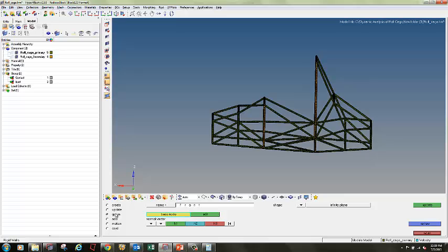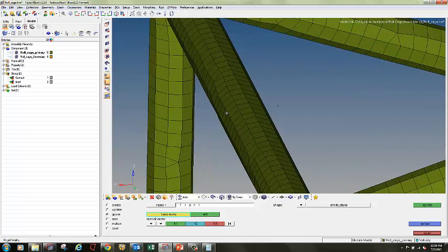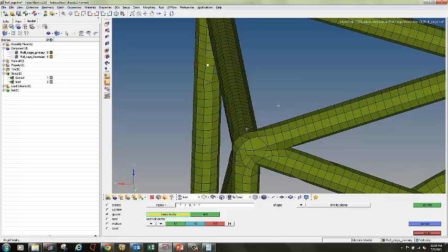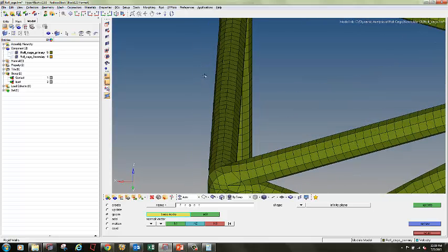Select the radio button as geometry. Select the base node at the front. I will select this. Go to edit. I want this node to be some distance away from the roll cage, so it will travel some distance, then impact and then bounce back. I want this node away in this X direction, so I will increase the length to 1420 and click on return. So you can see I am creating a rigid wall 10 mm away from the roll cage.